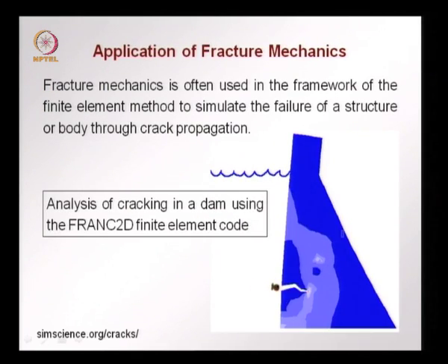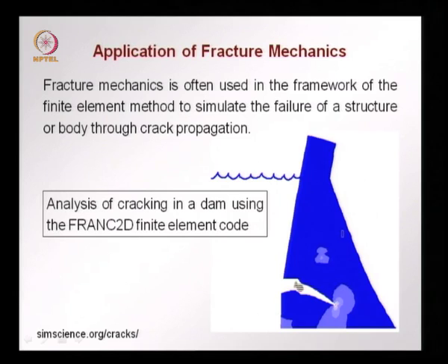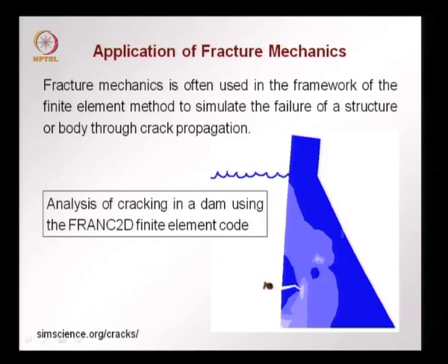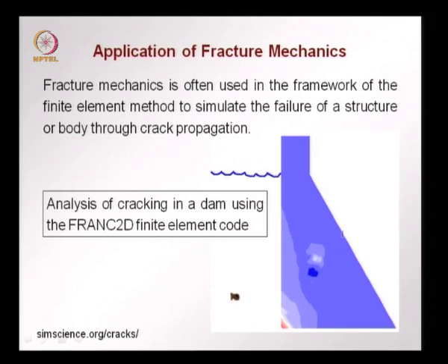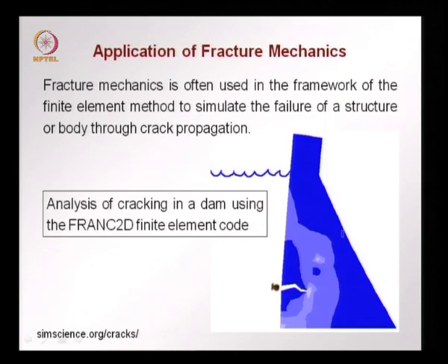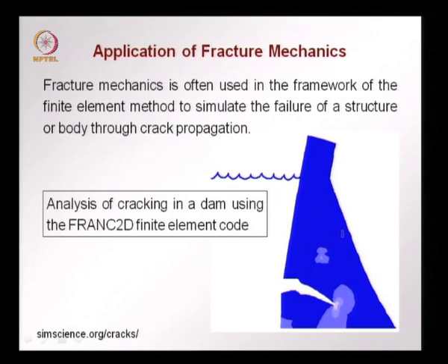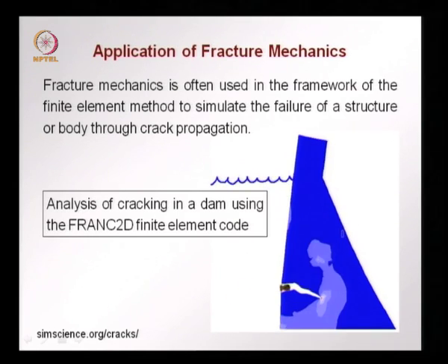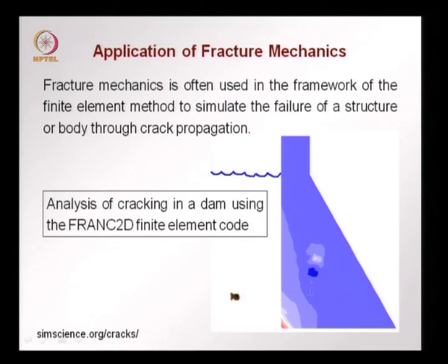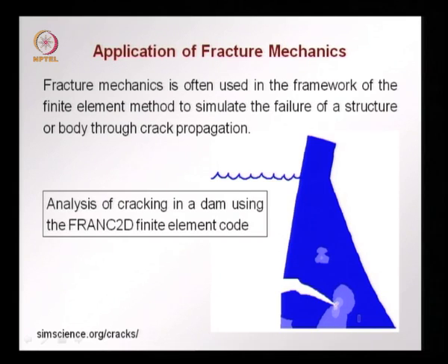So, let us see some simulations. This is from Sim Science, where we see the simulation made by Franc2D, which is a finite element code coming from the group of Professor Tony Ingraffea at Cornell University, where they have used fracture mechanics to simulate what happens in a dam that is subjected to excessive height of water. The pressure of the water creates a crack in the dam and you see a crack propagating. The red zone is where we have a very high stress concentration, and we see how the model is able to show how the crack will propagate and ultimately how the dam will collapse.